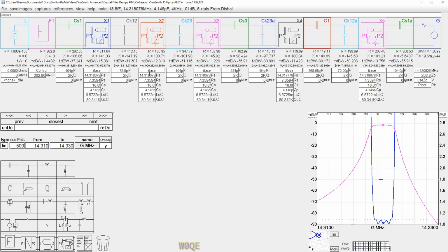And I'd pick those, and then to make these crystals, hopefully I could find some that would be a little bit higher in frequency, and I just adjust those up. Let me try that here and come back in just a moment with an example. Well, that was remarkably easy to do. I just randomly picked some numbers here. I said that crystal X2 would be at the lowest frequency for the filter.